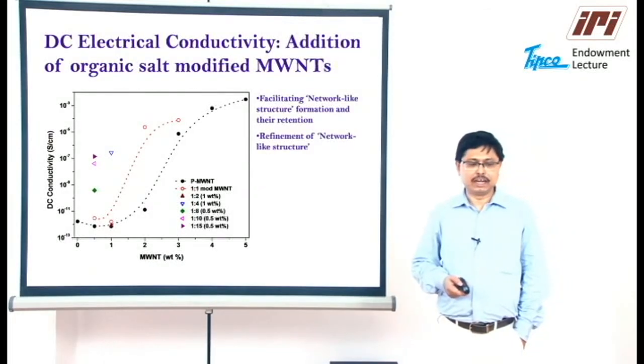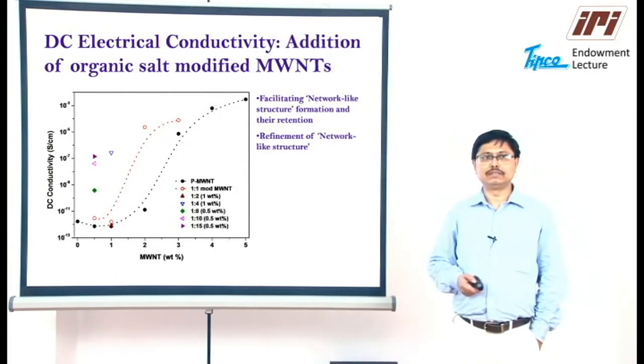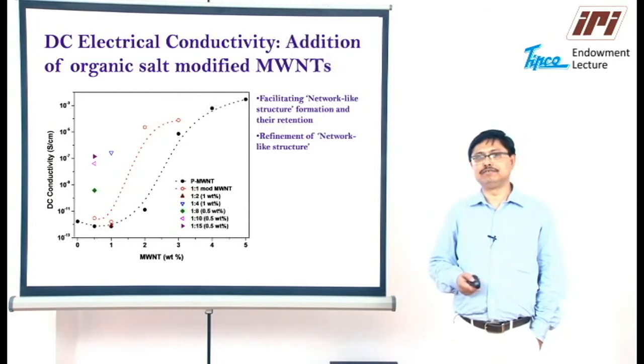One can also find the DC electrical conductivity for the various mixtures of multi-wall carbon nanotube and NaHA in the polyamide 6 matrix, and even at 0.5% the materials become at least dissipative in the conductivity range, with the percolation threshold shifting towards 0.5%.